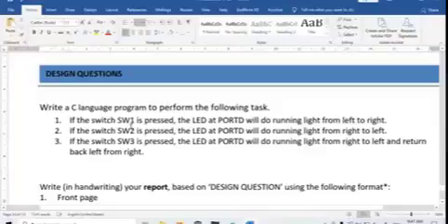You can use port B, port C, or port A. You cannot use port D, because it is already full, since you are connecting all the LEDs to port D. Therefore you cannot share port D with a switch. If it is not full, then you can also share, provided that you configure the direction register correctly.